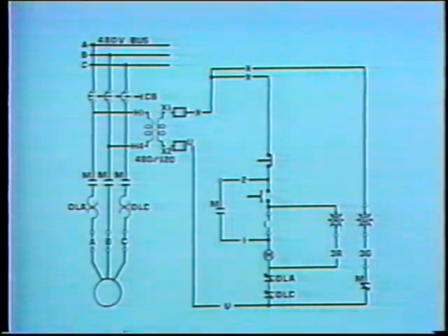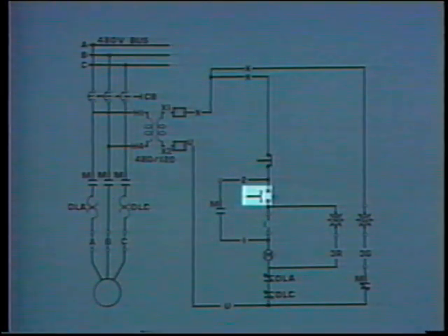The control circuit of this controller is open at the start switch. So when the electrician tests for grounds in the controller, he will have to test at the output of each fuse. This will ensure that he tests the complete circuit.